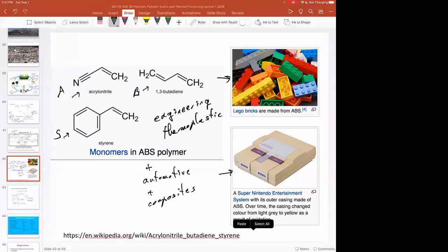And so ABS is a really useful polymer to get to know, and commercial grades, like I said, of ABS are sold. They're compounded to make composites, and we'll talk about compounding, but you see a lot of things made out of ABS. And it's also relatively inexpensive, because the monomers are relatively inexpensive.